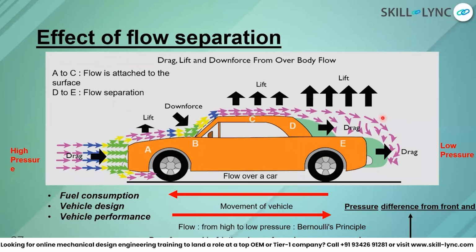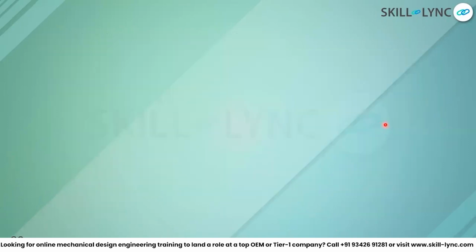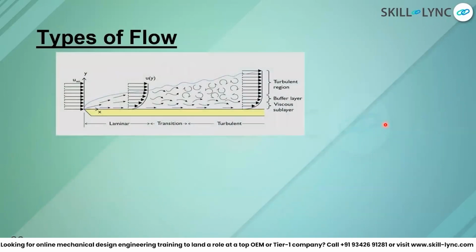Now, in reality, when a car is going on the road, there are dust particles, there is sand. That's the reason why you see sometimes that even the sedans or the hatchbacks have rear windscreens that are pretty much dirty if you go into a dusty place, if you go into places where the roads are not very clean, or if it is windy. That's one more thing, and that's the drawback of the flow separation of the car. It's not just the fuel consumption, but also the vehicle soiling. Okay, so that's one thing we have seen.